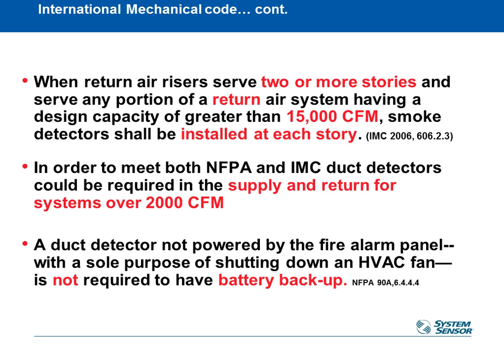So what happens if you're in a jurisdiction that does not require either NFPA or IMC? Does that mean you don't need to put a duct smoke detector in? Some of you probably would argue yes, that means you don't have to do it. But when something happens in the building and that air handler does not shut down and then continues to propagate smoke to the building, you're probably not going to be very happy at the result when you get sued because you didn't follow the general standard of care.